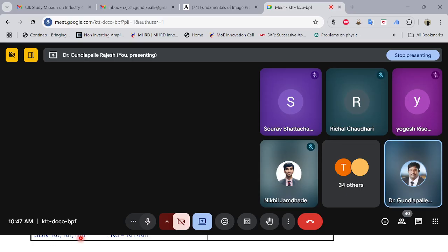Now we have division, signed division and unsigned division. In unsigned division, Rn is divided by Rm, and the quotient is stored in the Rd register. Then signed division is exclusively for signed numbers, whose MSB bit is 1.